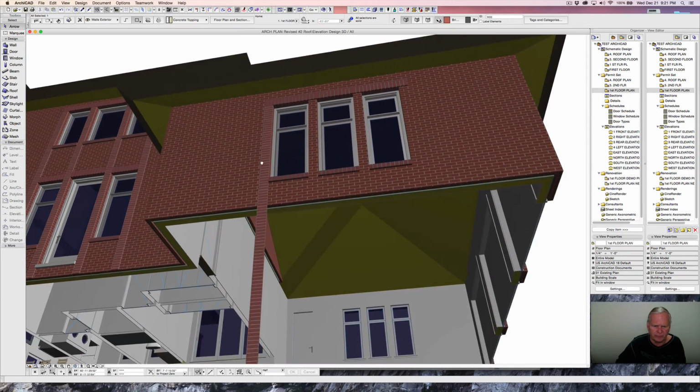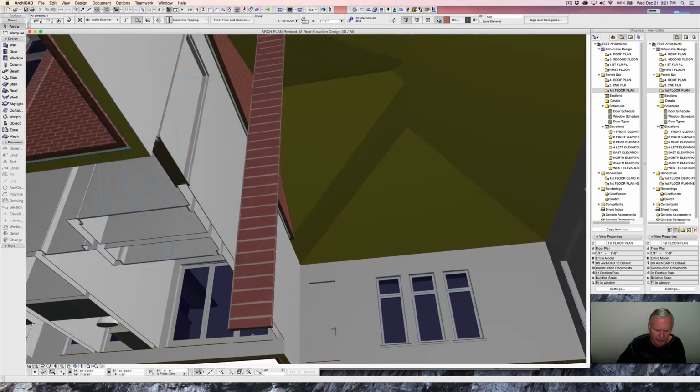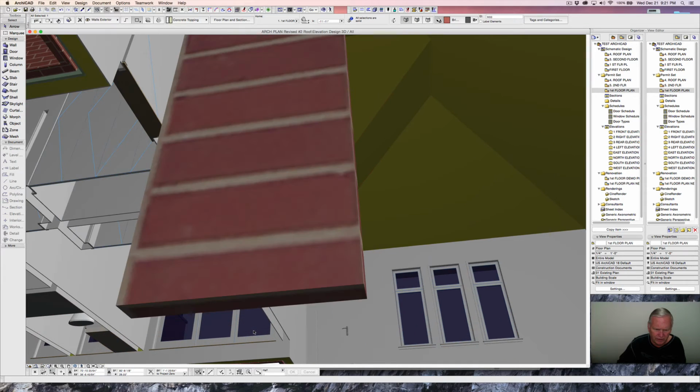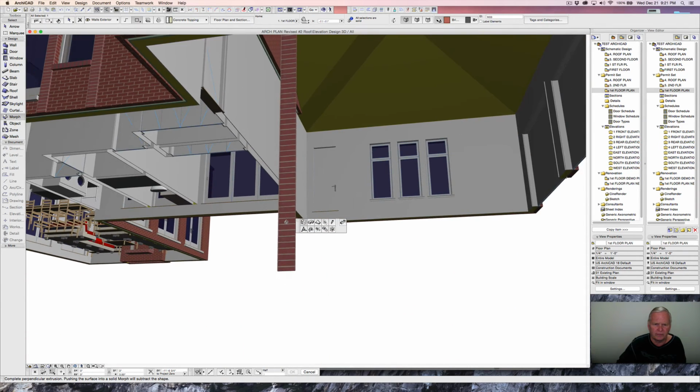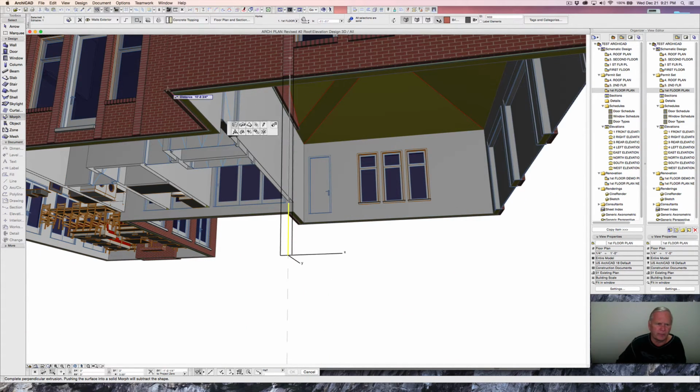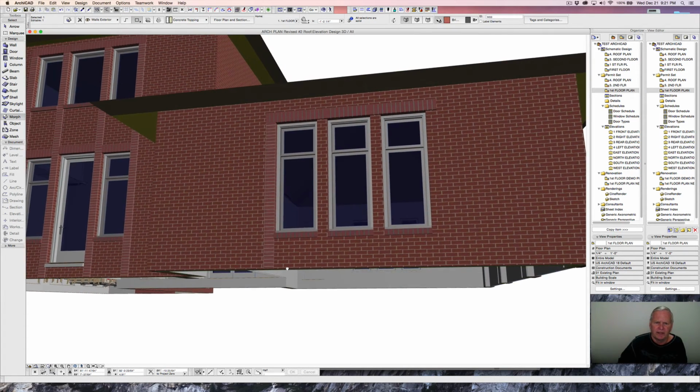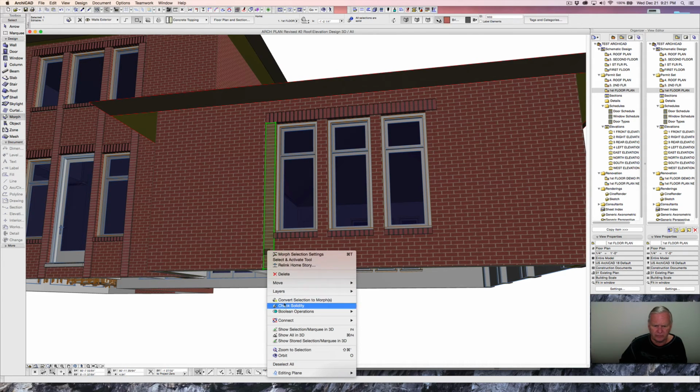Its height needs to be adjusted. So we'll come down here, zoom in on it. And we're not in the morph tool, so we'll just suck up the settings. That way I get that tool so I can stretch it and bring it up to the bottom, and I just go to a corner so I know I've got the bottom there. And now we can move, multiply.